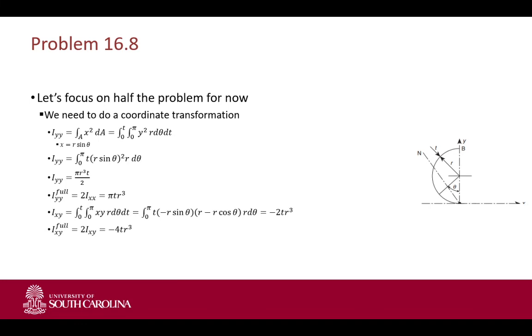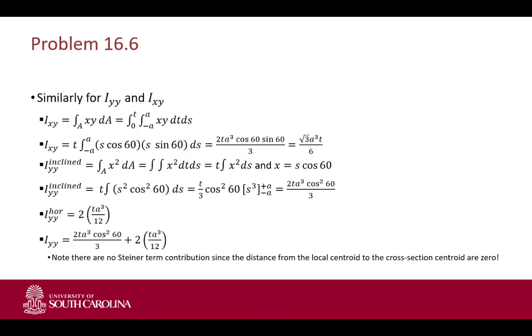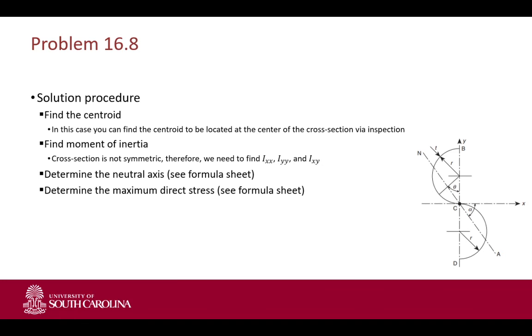In the slides, it comments on 16.2 that the cross-section is not symmetric. And why is it not? Yeah, that one. Just back one. Can you place a mirror and you get the same solution? It's not exactly symmetric. In what way? If you mirror it here, then you get a circle going like this, right? So if you mirror it on this, then the circle is again not the exact same thing. Okay. So it's axisymmetric, but not symmetric. So you can only say moment of inertia around xy is zero when it's a full symmetry plane. In this case, you call this axisymmetric. You don't apply that for the moment of inertia.